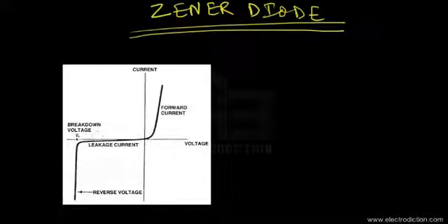We can see here that whenever a PN junction diode is reverse biased down to the breakdown voltage, right over here with the red mark, that is, whenever the reverse voltage across a PN junction diode is equal to the breakdown voltage, we shall see a sudden surge of current through the reverse biased PN junction. We discussed its cause in the previous tutorials, where we discussed breakdown phenomena.